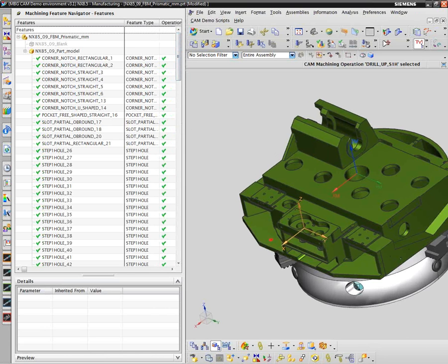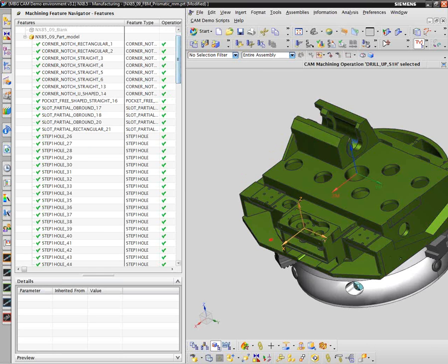And NX can identify about 60 different feature types, as I said earlier, and we can find them all together in one step, or apply various filters to be more specific in finding the desired features, and we'll show that a little bit further in our demo. What we see in the list is features that we found by applying some of these specific filters.